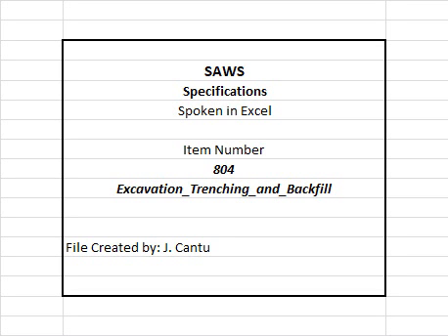D. Test requirements above are indicated as a minimum requirement, but may be subjected to more stringent requirements as established by other appropriate agencies, such as COSA Public Works Right-of-Way Management Plan, etc. E. Any failed test shall require the contractor to remove and replace that layer of backfill in the identified section of the failed test location to the trench depth and a length 50 feet in both directions, then refilled and compacted to the grade and compaction level required.